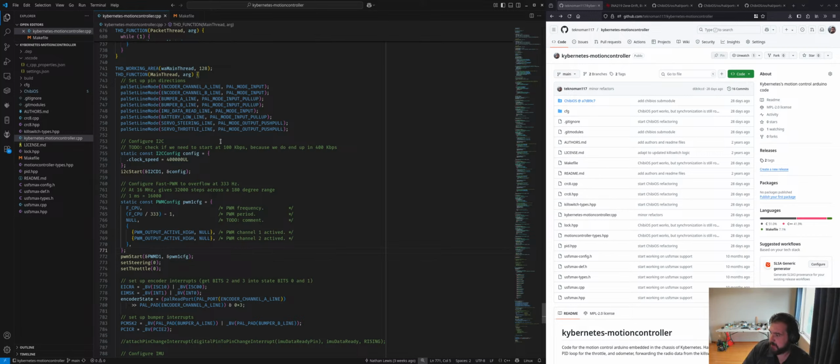What tickless mode does is it gets rid of that fixed interval tick interrupt. Rather, any time the kernel's going to sleep or doesn't have anything to do, or knows there's an event that needs to happen in the future, rather than just waiting for the next tick, it'll set timer 1, a higher accuracy timer, to throw an interrupt specifically at the time the next event occurs, rather than waking up, finding there's nothing to do yet, and going back to sleep.